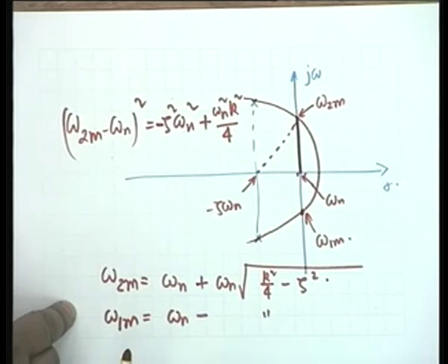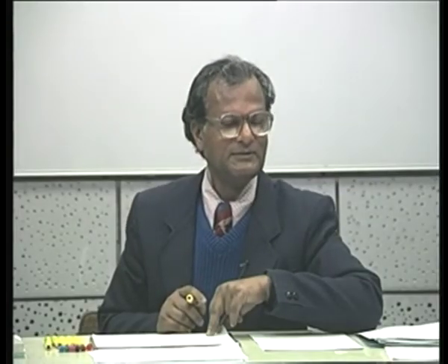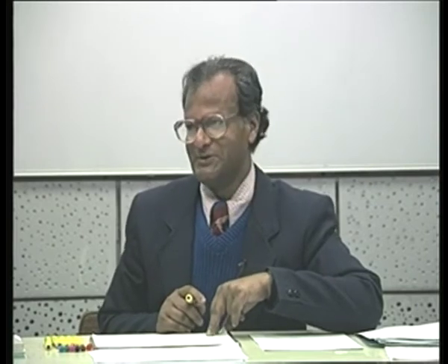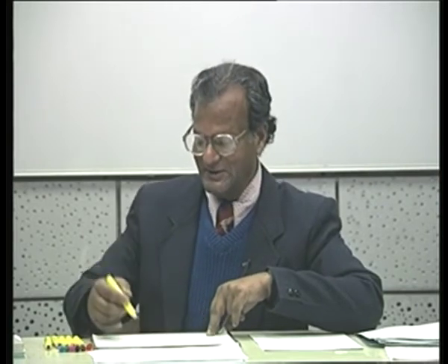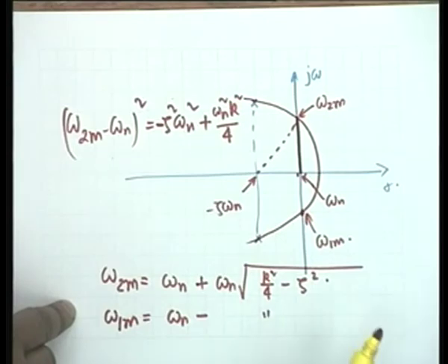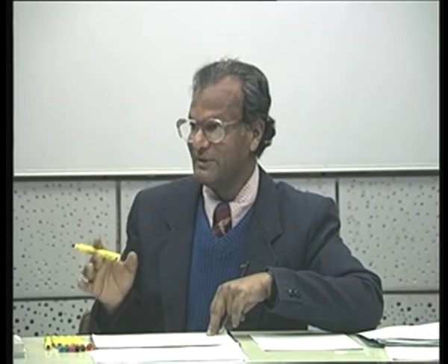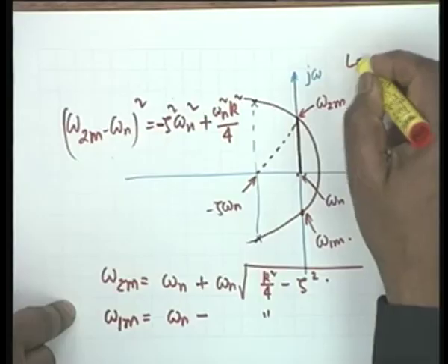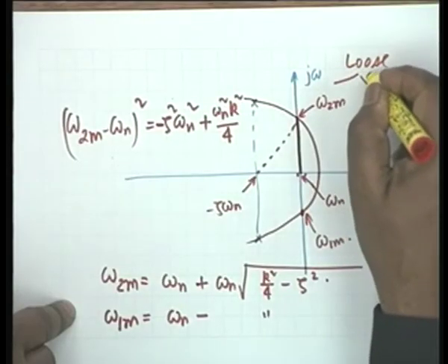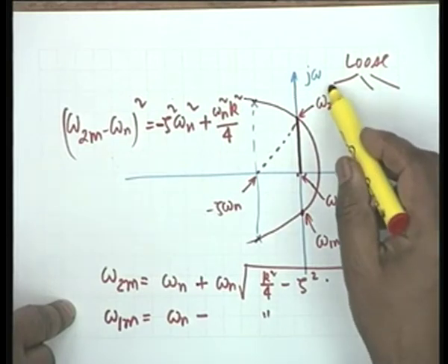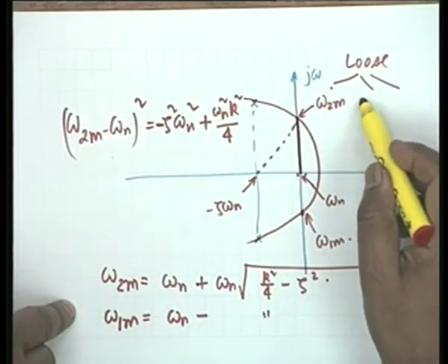Assumptions were that the damping was very small and the coupling was loose, but at the same time double peaking occurs for the over coupled case, over coupled under loose coupling. Loose coupling has 3 stages: under coupled, critically coupled, and over coupled.